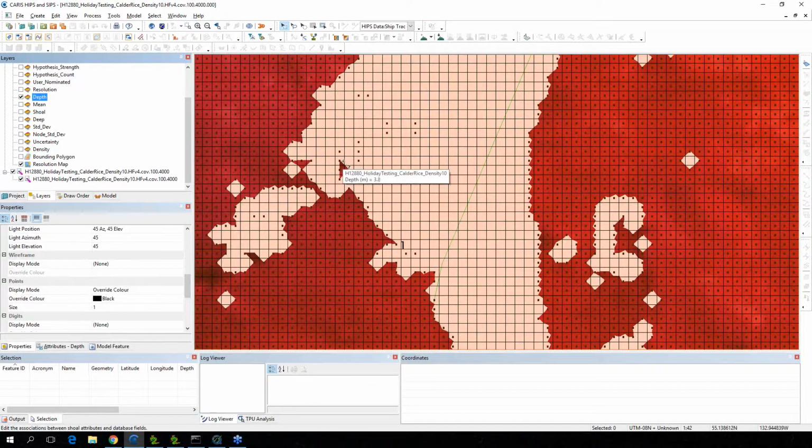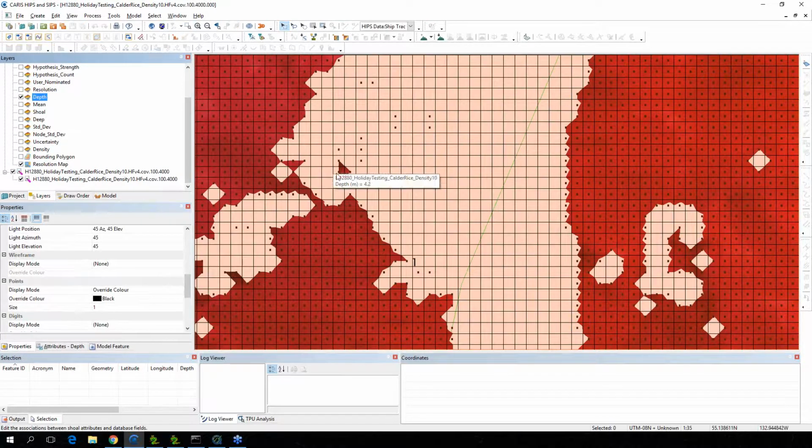So you could see here this area where I'm kind of circling with my mouse, right? But these points don't actually show up in either the wireframe or the surface view, because they have either, say, 0 or just one neighbor. But as soon as it has 2 contiguous cells, sorry, I believe it's 2, then it will draw the mesh between it. But when it just has 1 contiguous populated cell, it's not going to.